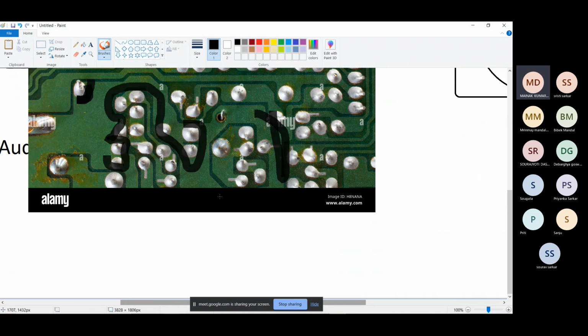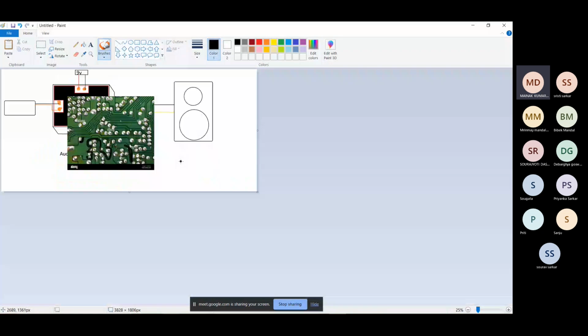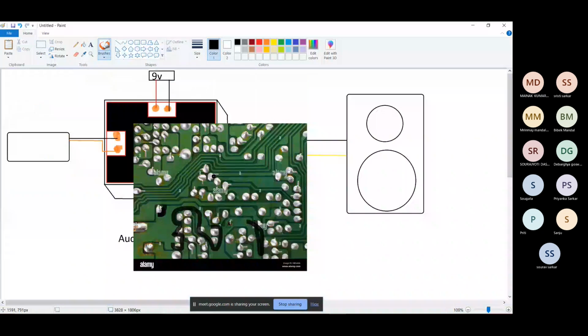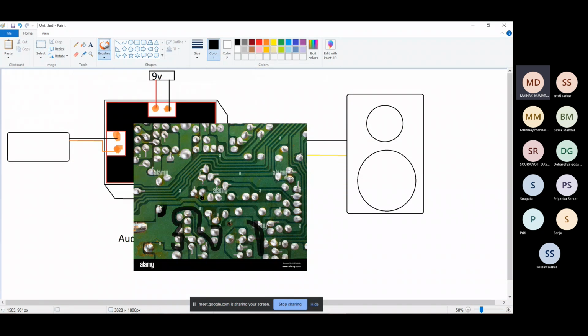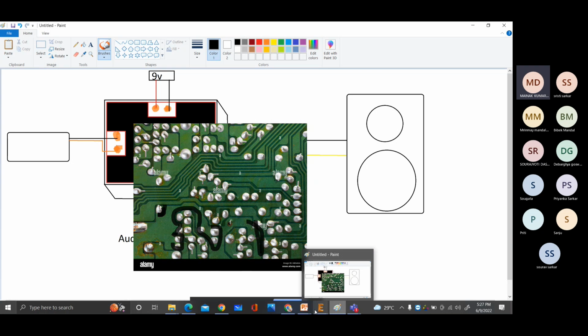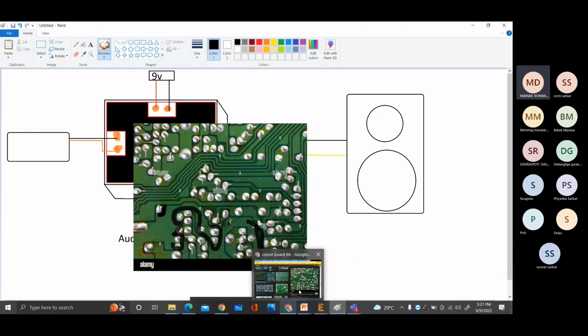It looks more professional because most of the PCBs have this kind of concept. Most of the PCBs have this kind of feature, that every ground portion or every ground pin is connected with the help of a ground plane. And if you go without the use of a ground plane, just see the circuit.